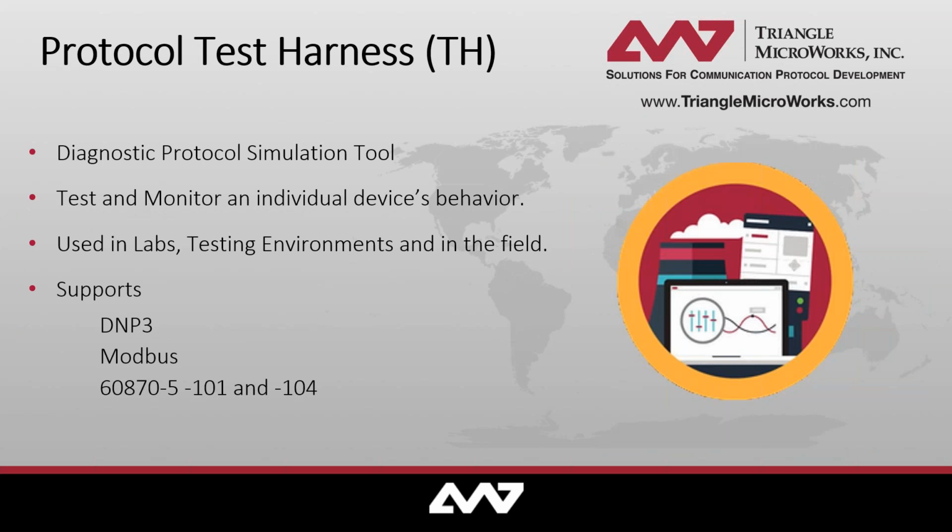The protocol test harness is an application we'll be looking at the most today. The test harness is a diagnostic protocol simulation tool used to test and monitor an individual device's behavior. It can be used in a wide variety of situations, including in development, in testing, in labs, and even in the field. The test harness supports DNP3, Modbus, 60870-5-101, and 104.